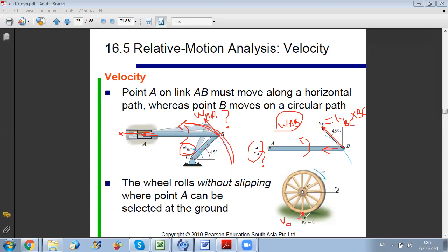Okay, this is what we call the instantaneous center of rotation. It means that at each instant all points seem to rotate about this point, and this point is changing with time. This is why we have a general motion. For example, here point B is just doing translation, moving along a straight line, while other points have different velocity vectors. Each point has a different velocity vector and we don't have a fixed axis of rotation. The center of rotation is varying with time. So this is also a general plane motion.